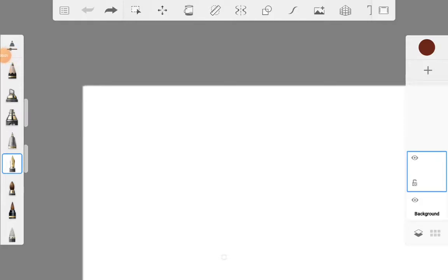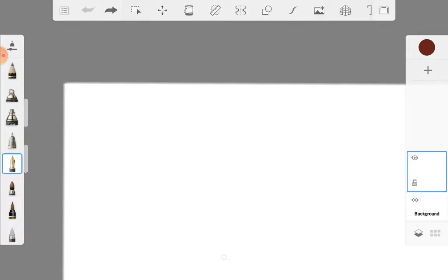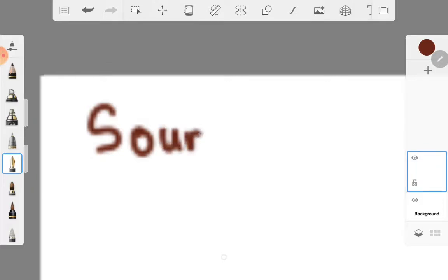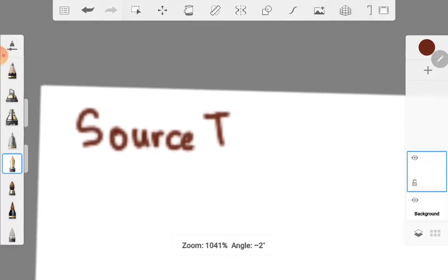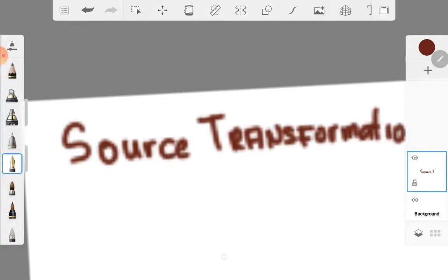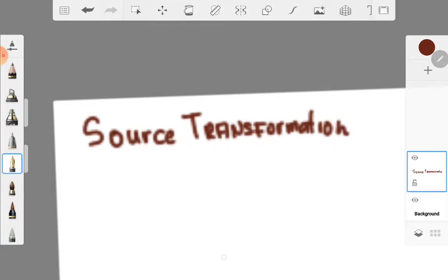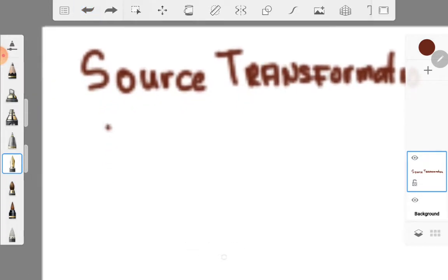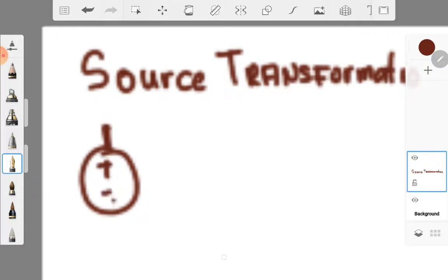So in this video presentation, I will discuss source transformation. What is source transformation? According to the source transformation theorem, you may interchange or substitute a voltage source with a series resistance into a current source that is a parallel resistance.